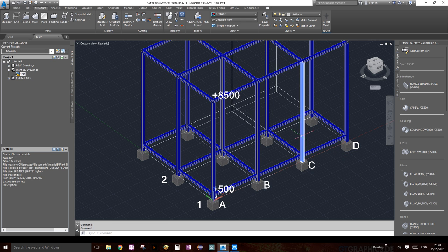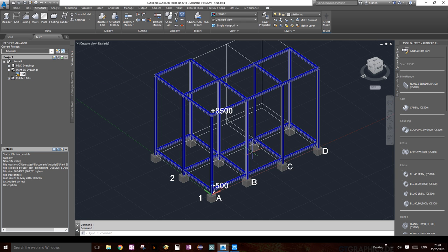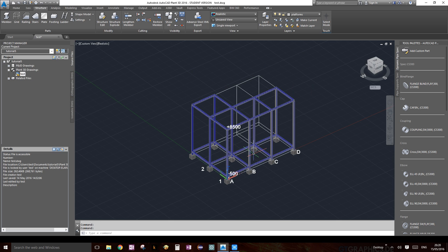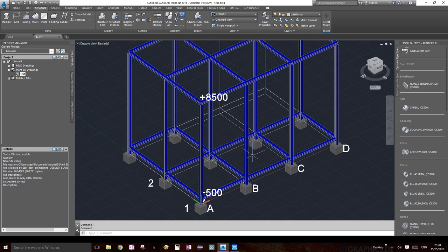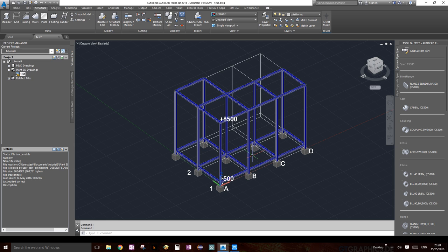Okay, so another thing that we're going to use on and off quite a bit is the properties window. I find that it's sometimes super easy to just change the numbers rather than physically change the object. So in that case, you can just go into the properties window and quickly change some of the attributes. To open the properties window, as long as you're in AutoCAD, just start typing properties.